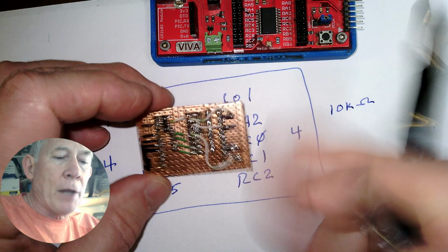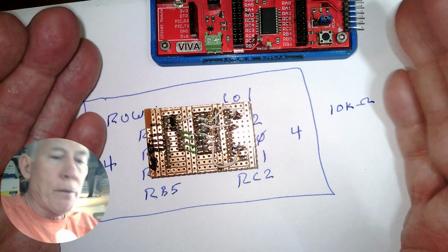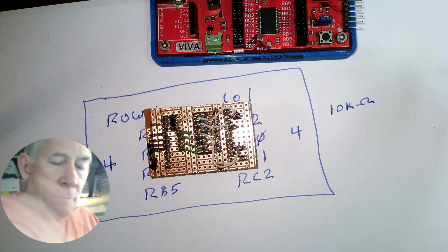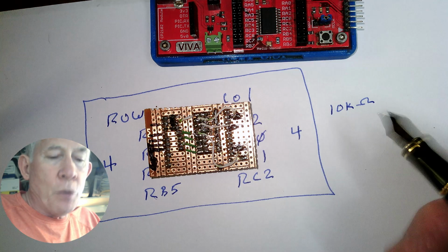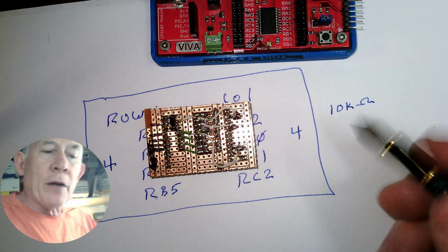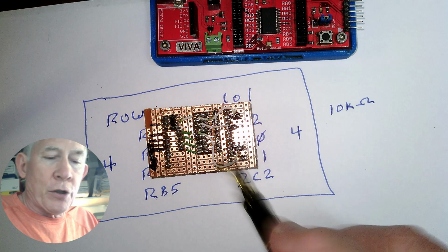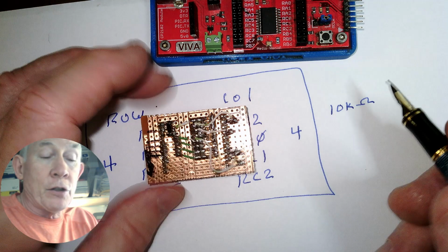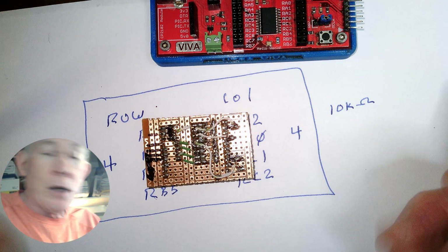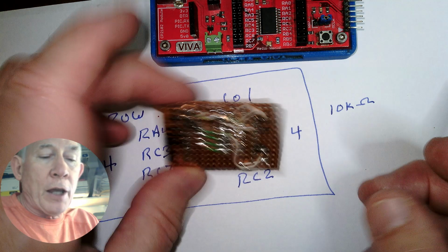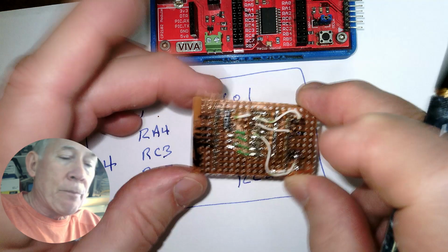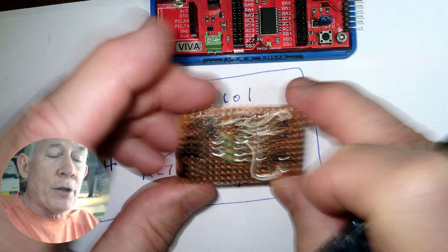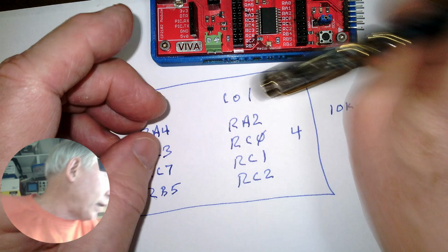Now, if you try and put all this stuff on one of those proto boards and plug stuff into it, you will find that things wiggle around and your resistors may stop working. It may get bumped and not be fully connected. You may have a wire pop out and then you're trying to figure out where to put it back in. So whenever you can, it's really good to take some of this copper, this perf board with one layer of copper on the other side. And let me show you how that's set up.